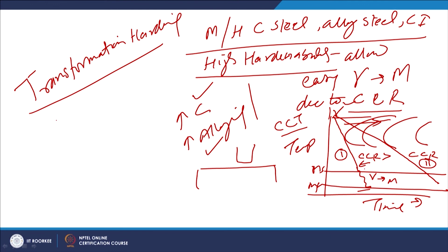When the critical cooling rate is high, especially in low carbon steels or when the alloying concentration in the steels is less, it is difficult to transform austenite into martensite. That is why medium and high carbon steels, when heated high enough to the austenitic temperature range followed by a cooling rate which is high enough, not very low, will facilitate the austenite to martensitic transformation for the required hardening purpose. So, the basic principle in this approach is that we use a suitable heat source.